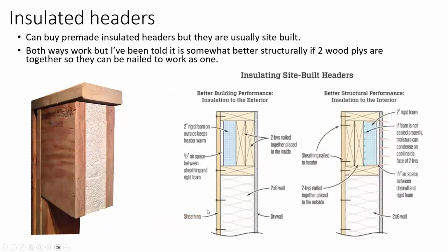Now let's talk a little about insulated headers. I've seen them made all three ways, believe it or not, on site. I've seen them where they make it like an insulation sandwich, where you have rigid insulation in the inside and then you have a ply on the inside and the outside. I used to do that all the time when I was doing houses.